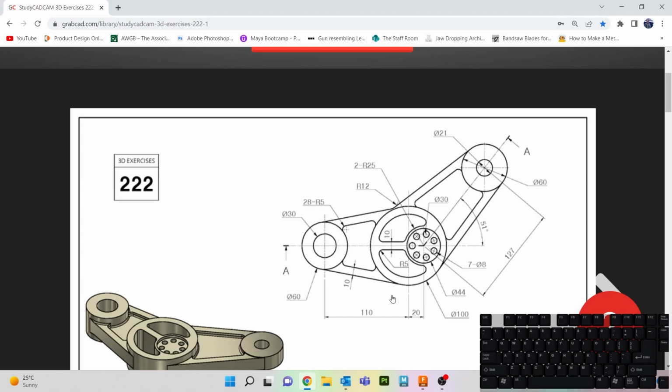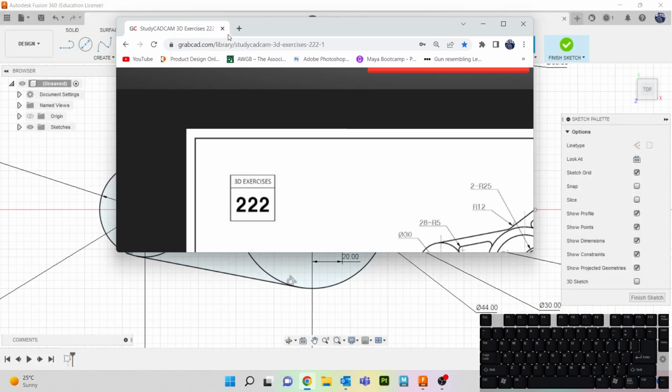You do have to be careful sometimes, as there might be missing dimensions every once in a while. Right, let's just do what we know. So I'm going to do this circle here of radius 25, and I'll do that line there that we know about. It will then just be this circle, but I'll come back to that and then we'll do these. So here we know this one is parallel lines from there, and then it's a distance of 10, and then it's just a fillet of 5 as well, which is quite easy to do. So we can do that as well.